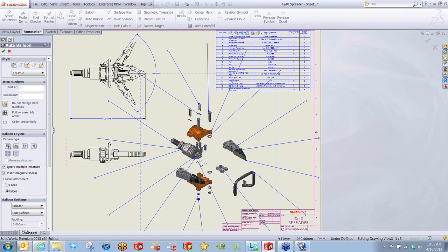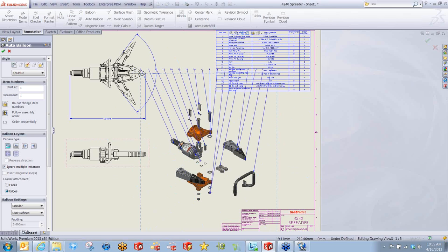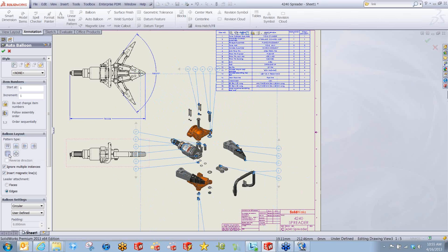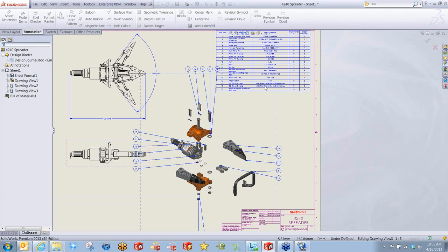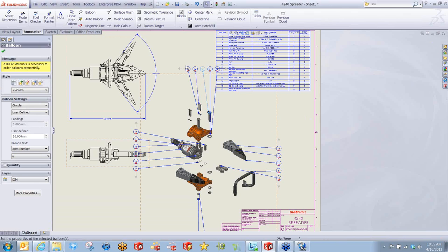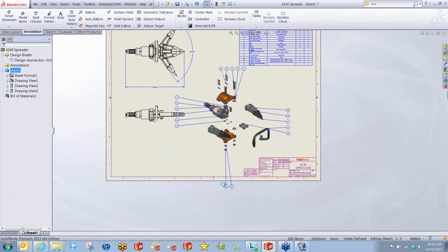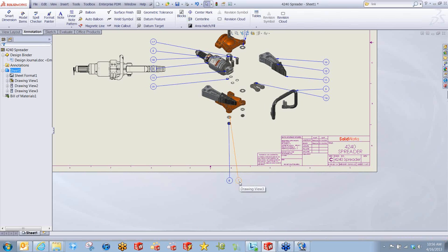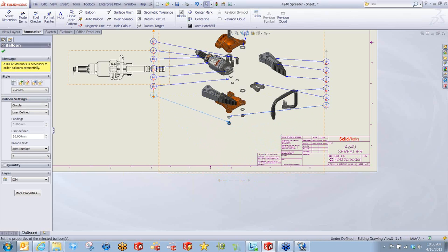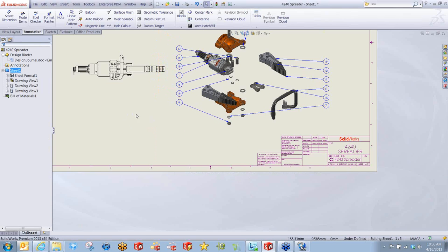Okay, we could try a range of different positions, styles, layouts. Okay, maybe we want most of these balloons on the top, on the side. Okay, I'm going to go all around though. All right, we'll hit OK. But now our new magnet tool, I can come quickly grab that whole group of balloons, put them in a slightly better position that makes more sense for my drawing. Okay, we could even pull balloons off of magnets and snap them to other magnets. Or maybe it makes more sense to have those. And then again, we'll slide these in as a group.